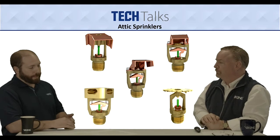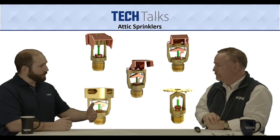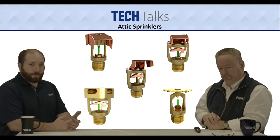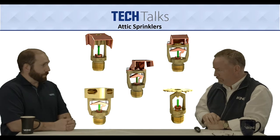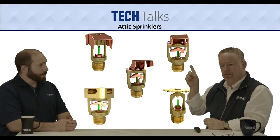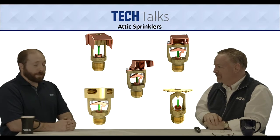Right. So the really cool thing is attic sprinklers. Viking's developed quite a number of them. I'd say we have probably one of the largest families of attic sprinklers, so we can suit just about any challenge in an attic. On the top there, we've got the back-to-back, the VBB, which is going to spray water to both sides, positioned at the ridge and shooting water down each slope. We've got single directional sprinklers, which are going to spray a little farther. This one right here. But they're going to spray down one single slope.